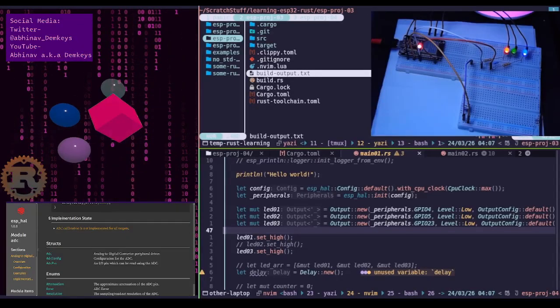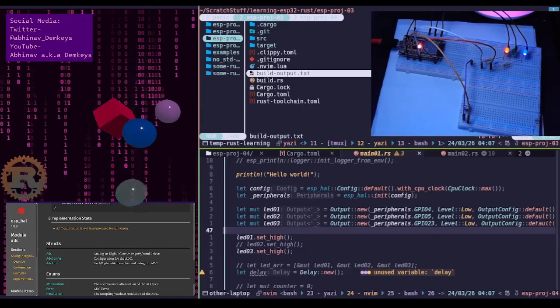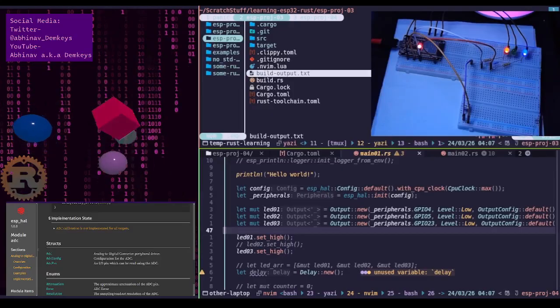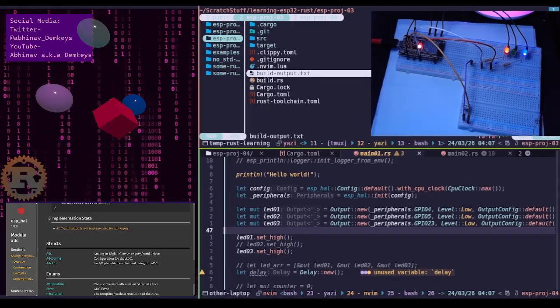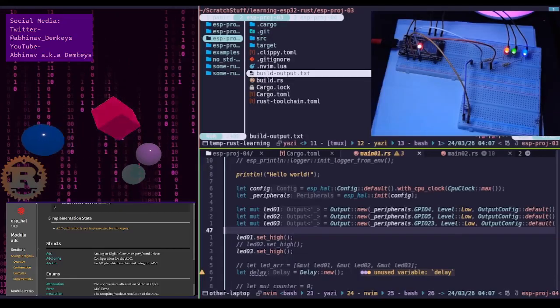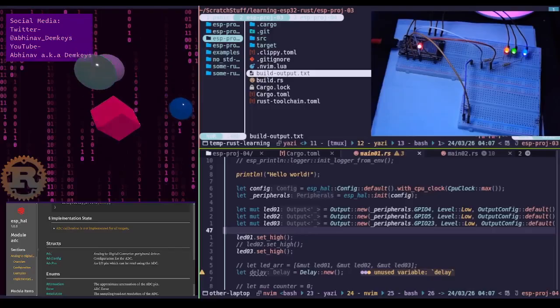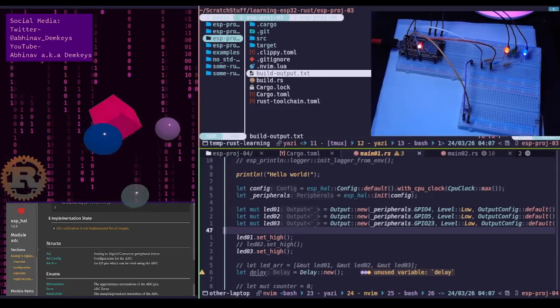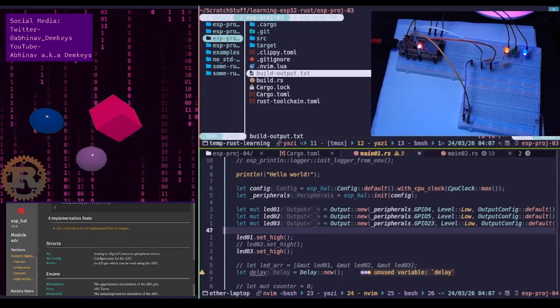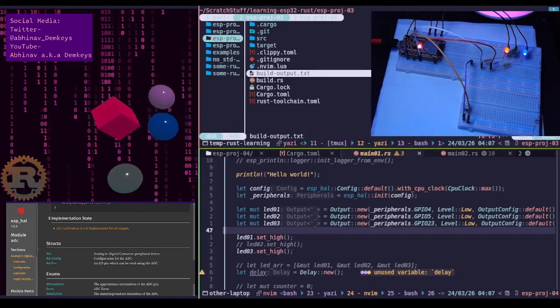When the HAL says calibration is not implemented, it means the chip doesn't know its own specific line yet. Why the line matters: think of the ADC as a machine that translates X volts into Y digital units. That makes sense. M is the slope. This represents the gain. If the slope is too steep, your readings will rise faster. Okay, that makes sense.